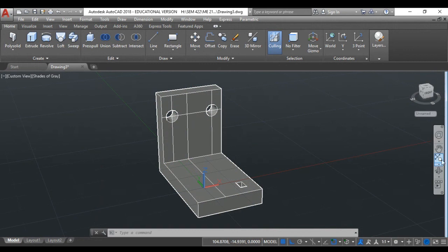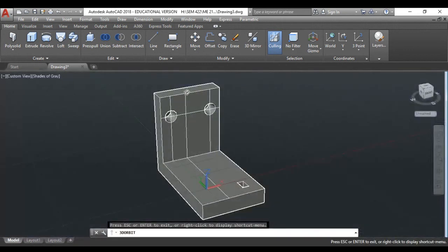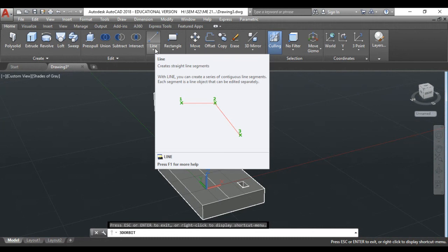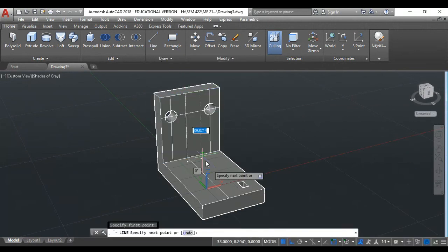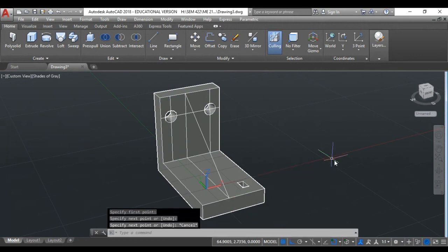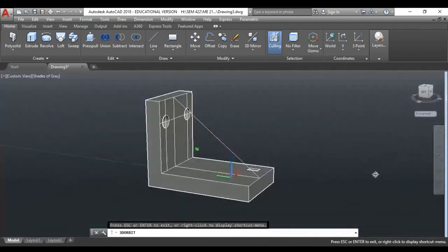So what should I do next, guys? What is the next step after drawing these two lines? Just connect the two ends together. Right? So I'm gonna use line again; it's not required of you to draw with the user coordinate system, because you are forcing the program to draw from a certain point to another certain point. You got it? So you draw a line from that intersection there all the way until you reach that intersection. Here you go. And that's it. How did I guarantee that this triangle was drawn the way I like? Here you go, guys. You see?